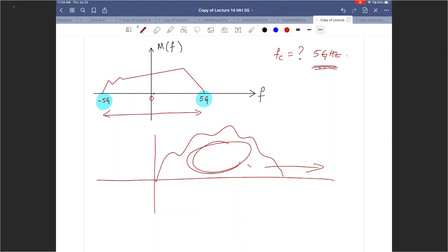And in order for me to transmit that, I need a carrier in the RF frequency range, maybe hundreds of gigahertz at least. So what I'm doing when I do that upconversion is essentially increasing the frequency where that bandwidth is located, right? The bandwidth is going to be 10 gig, no matter where it is.